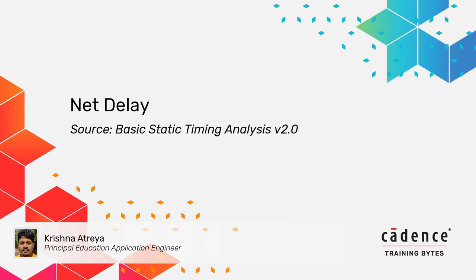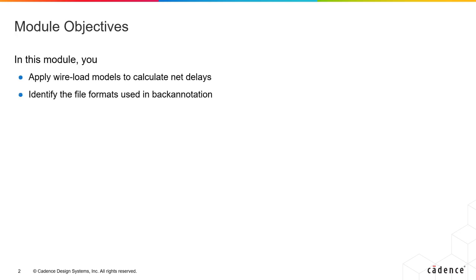Let's look at how the tool calculates net delay. In this module, we'll look at what wire load models are and how they're used to calculate net delays. We'll also identify the different file formats that are used in the various tools that represent the wire delay information.